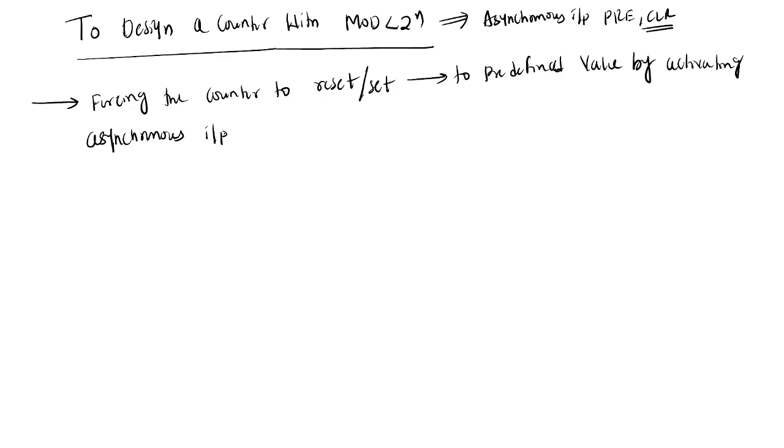And next, suppose the logic for clear or set depends on whether the flip flop has active high or active low pins. If the flip flop has active low clear, you need to use NAND.